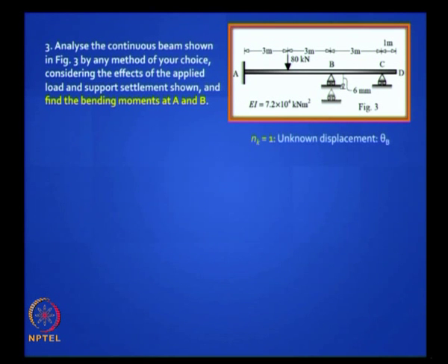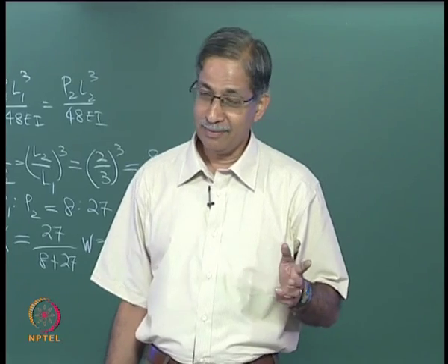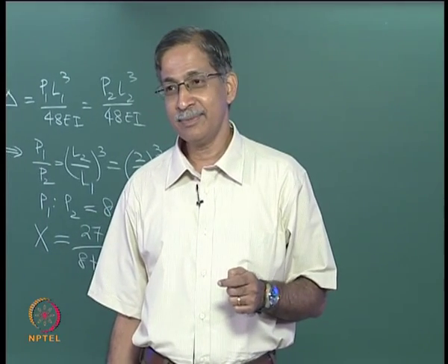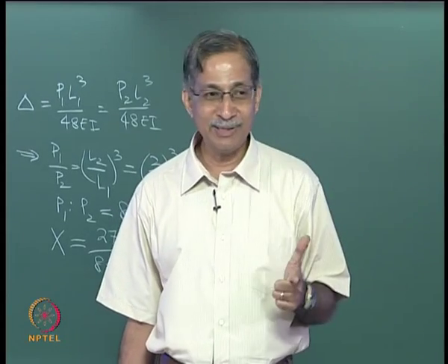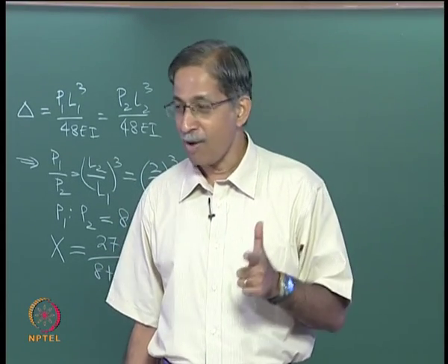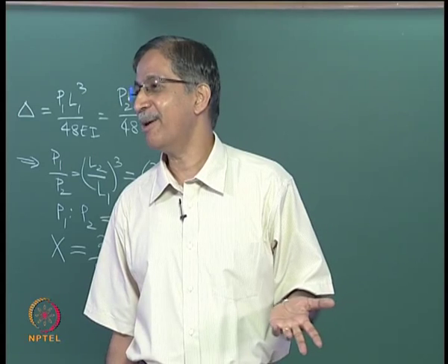Third problem, you had a 2-span continuous beam with an unnecessary overhang which was just meant to fool you. You can throw it off in your analysis, it's a simple standard problem. Which method will you choose? You are told to do any method you want. Half of you did theorem of least work, method of consistent deformation. Nothing wrong, but you will have less time for other problems.